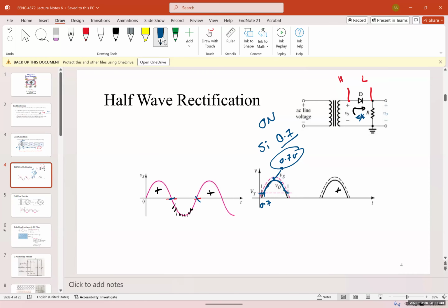And then it's going to cut again here at 0.7, and you're going to have it turning on again here at 0.7. So you can see the difference between these two is wasted, and also all of that is wasted, and this power down here is also wasted. So again, efficiency around 34%, I would say. Okay, and we showed the efficiency.